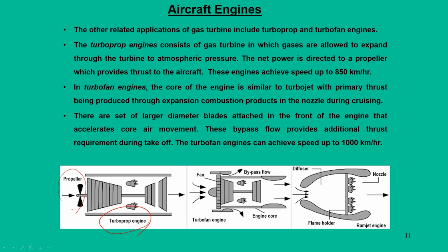And the other extreme case is where there are no turbomachine devices. It is a simple duct, and in the duct, whatever pressure difference is created, is created through the geometry of this duct. So, we call this a ramjet engine. The shape of this duct essentially changes the pressure and temperature conditions within the medium.